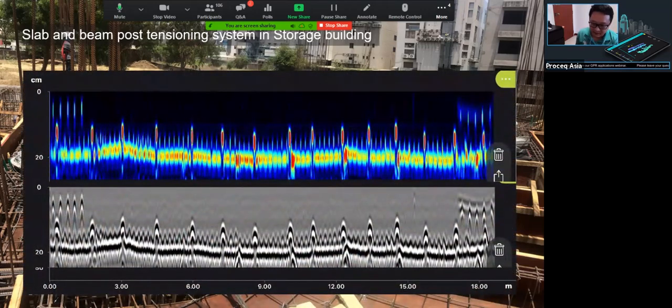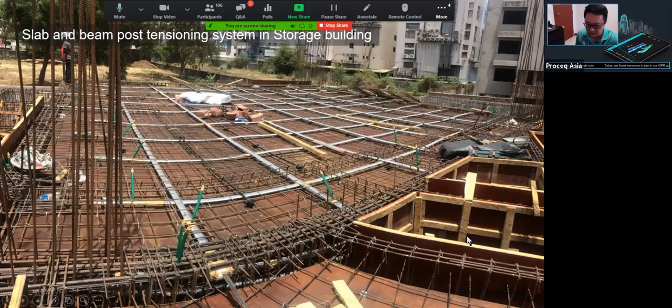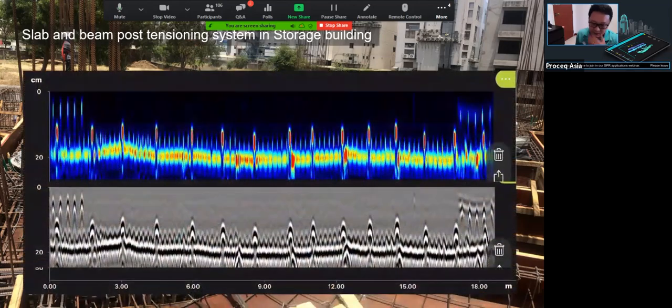So I put up two results, with the magnetic view on top and the non-magnetic view below, right? So you can see all the rebar from the non-magnetic view, right? There's a cover from the beam location. That's the first layer rebar, including the second layer rebar. And for this case, actually, there's no top layer, only the bottom layer rebar below the post-tensioning cable.